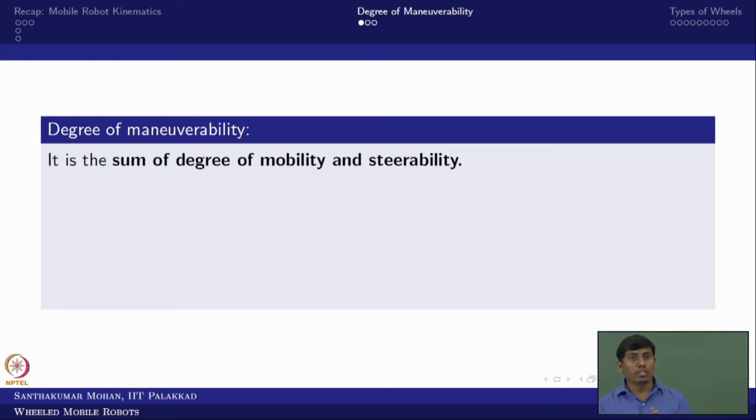You know the system we call a land-based mobile robot has a fixed degree of freedom, because it moves on the plane, where 2 translations and 1 orientation are required to describe the position of the system. Whereas the degree of maneuverability comes from how the wheels are arranged, in the sense of which wheels are powered. The degree of maneuverability is straightforward: the number of controllable inputs.